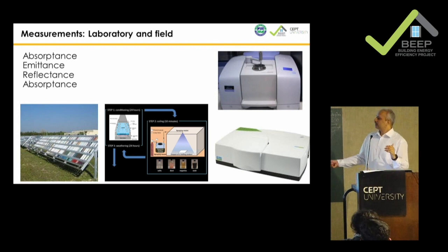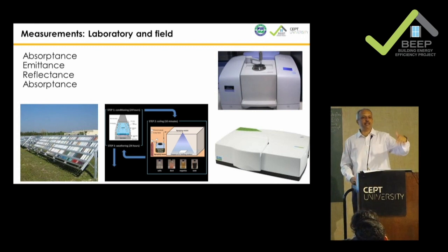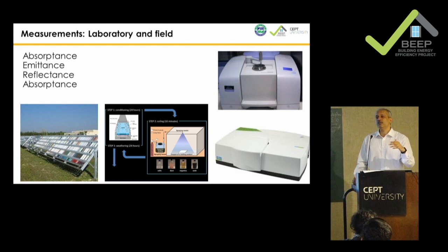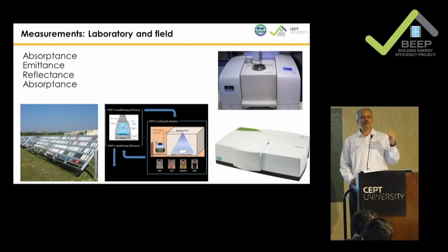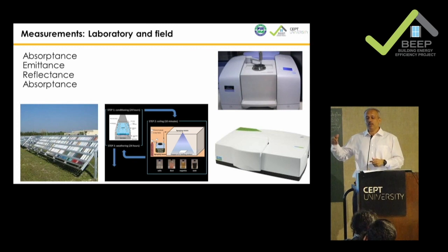So there are other tests for which we are still developing the methodology, on how it degrades. We do accelerated testing of what happens in the real world over a period of 3 years, to understand whether this paint will remain like this or degrade 10%, 5%, 30% over 6 months, 8 months, 9 months, 2 years, 3 years. And then you decide the performance of that.